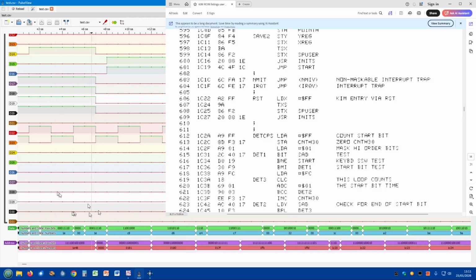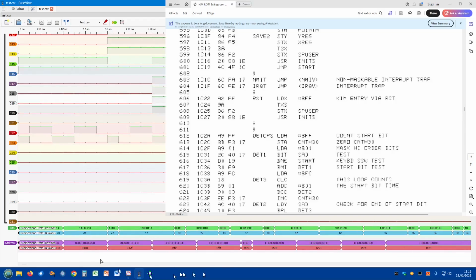So it's a bit of gibberish to start with. The 6502 does a few bits and pieces. There's 6 clock cycles before it actually starts processing. And the first thing it does is load the vector for the start of the program into the program counter. So it looks at addresses 1FFC and 1FFD for the reset vector.